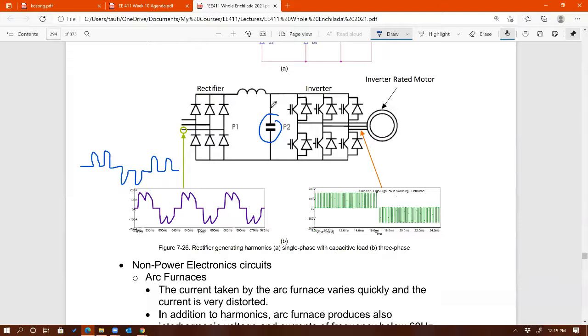As you are charging this cap, you have voltage at the cathodes of the diodes. So as soon as the sine wave at the input is larger than that voltage, the diode conducts. So it takes time for that, and that's why you see this discontinuity in the current.